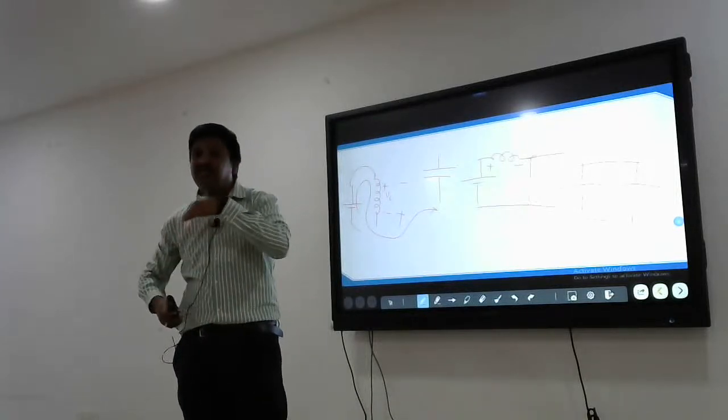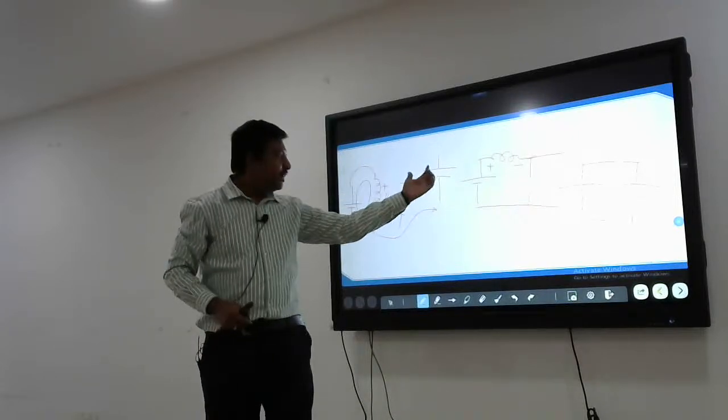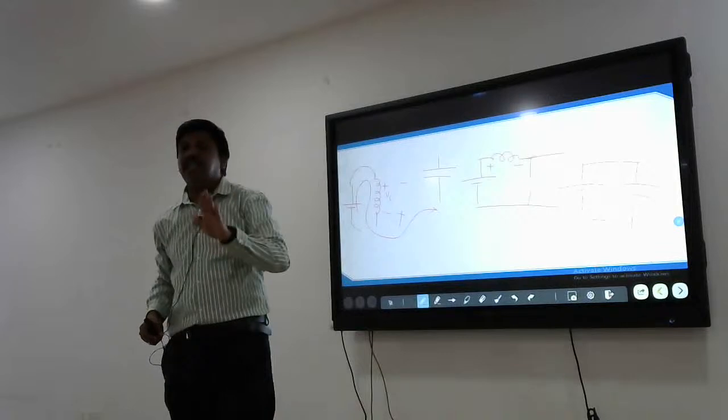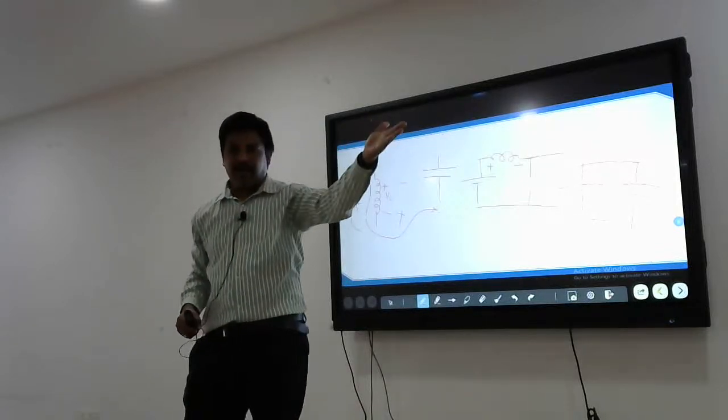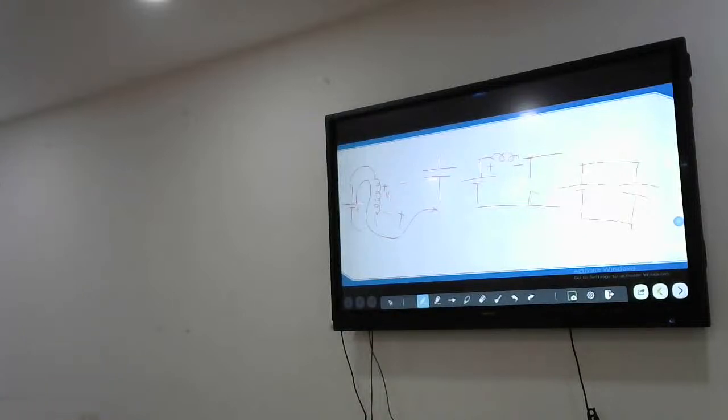The inductor voltage polarity changes, whereas capacitor polarities remain the same, but you have to see the connection such that it is aiding the load. That is how we can develop high gain converters. So we have to use the charging and discharging potentials of both the capacitor as well as the inductance.